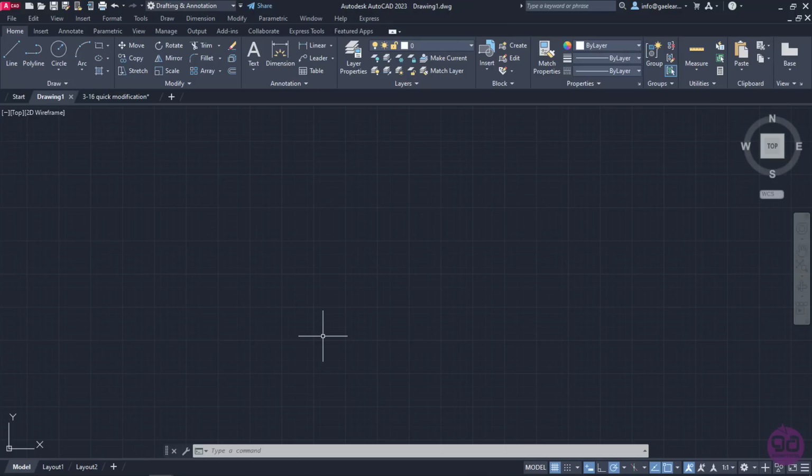So basically, dynamic input enables the tooltips command interface in the drawing area and provides an alternative way to insert a command, its value, and other subsequent changes to the command. Similar messages appear in the command line. The difference between the command line and dynamic input is that the dynamic input tooltips stay near the cursor.